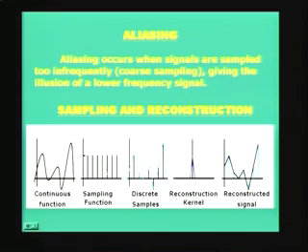Basically, what you do, you overlap the sampling function on the continuous function and sample it at regular intervals of time. So, wherever you get a non-zero value of the sampling function, multiply it with the continuous function value at that point in time, and that is where you get the discrete samples, which are the vertical lines here. The dashed line here shows the continuous function which is analog or continuous, and then you have the discrete samples.